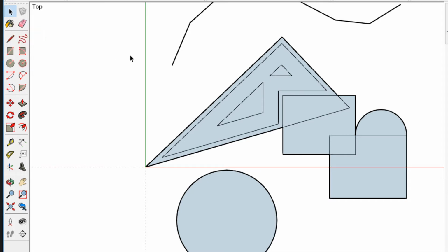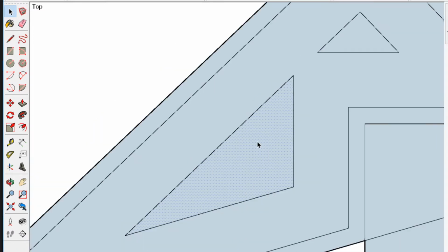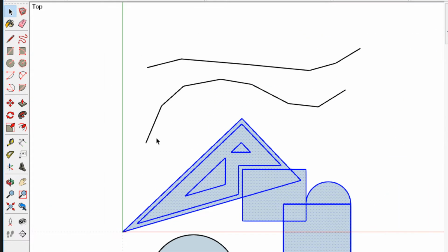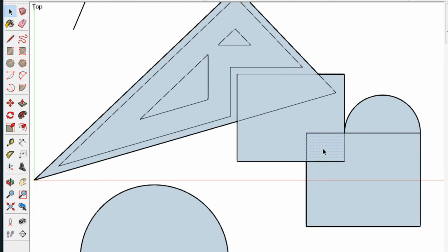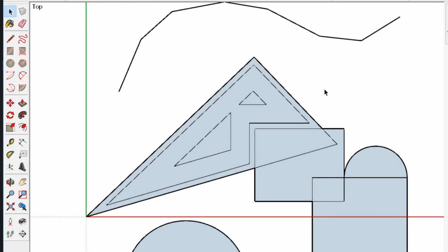Now basically we will go to what this is. Select, just press space, select. Click once to select the face, click twice to select the face with the edges, click 3 times to select anything that's connected with each other. Okay, again, once, twice, 3 times. The beauty of selection is Control, which shows a plus sign on the mouse, and Control Shift, which shows a subtraction sign on the mouse. Okay, plus sign to add selection, minus sign to subtract selections.